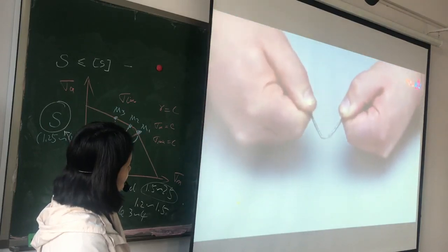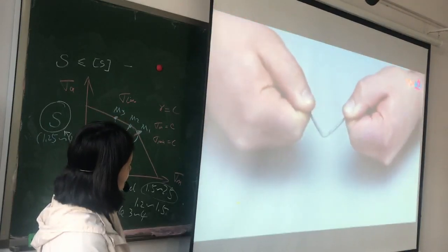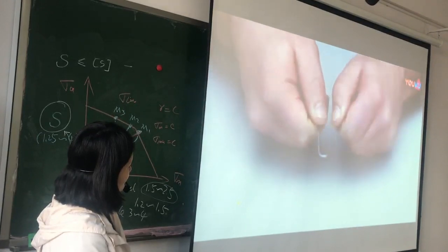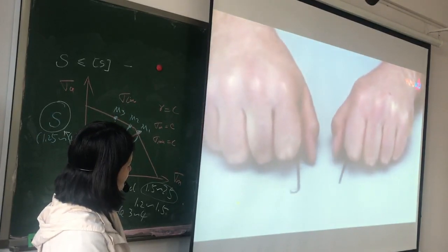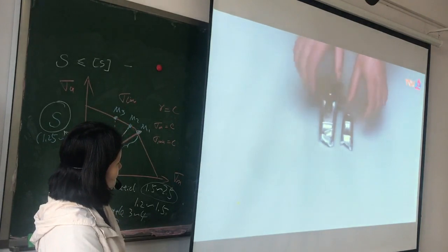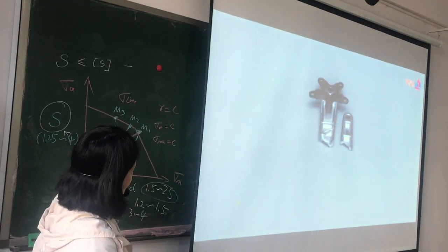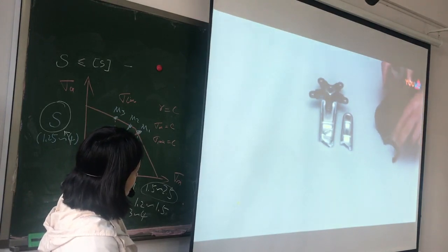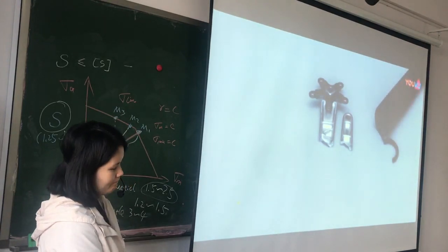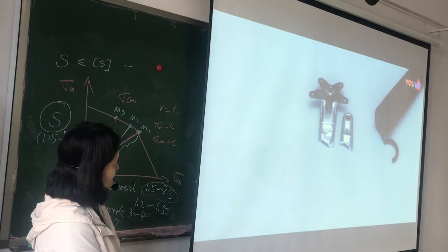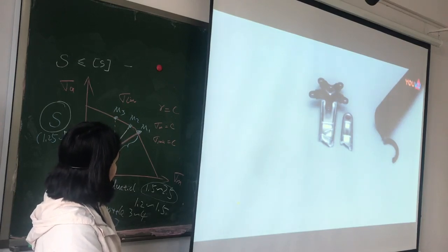The wire does not break when first bent, but bending it back and forth repeatedly leads to an early fracture. This bicycle crank arm had only been able to endure the cyclic loading for a certain time before it broke. The fate of the garage door spring was the same. It had borne the opening and closing of the garage door about 60,000 times before it finally fractured.